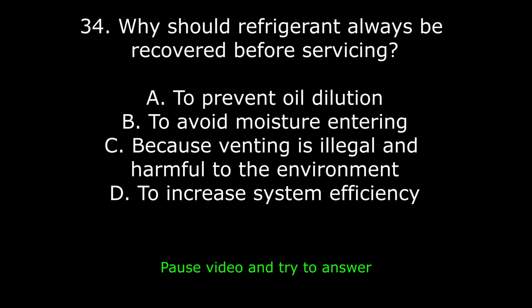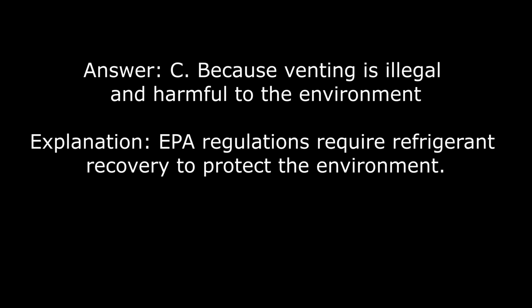34. Why should refrigerant always be recovered before servicing? A. To prevent oil dilution. B. To avoid moisture entering. C. Because venting is illegal and harmful to the environment. D. To increase system efficiency. Answer: C. Because venting is illegal and harmful to the environment.